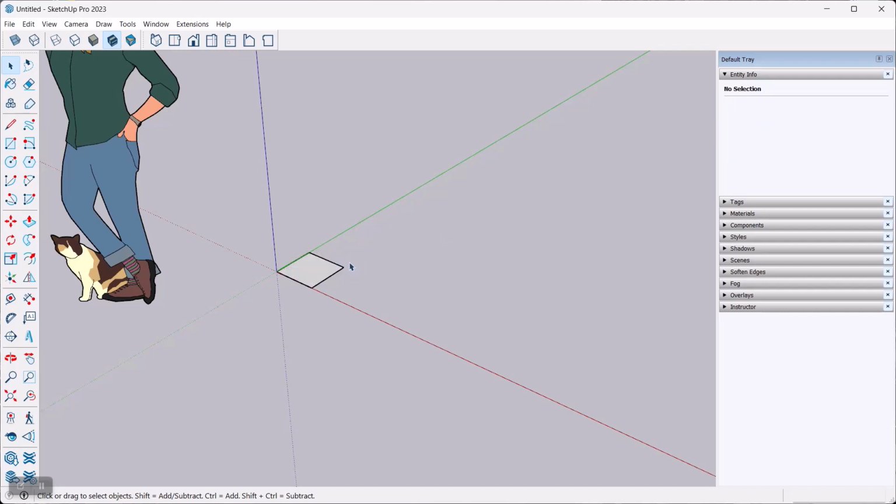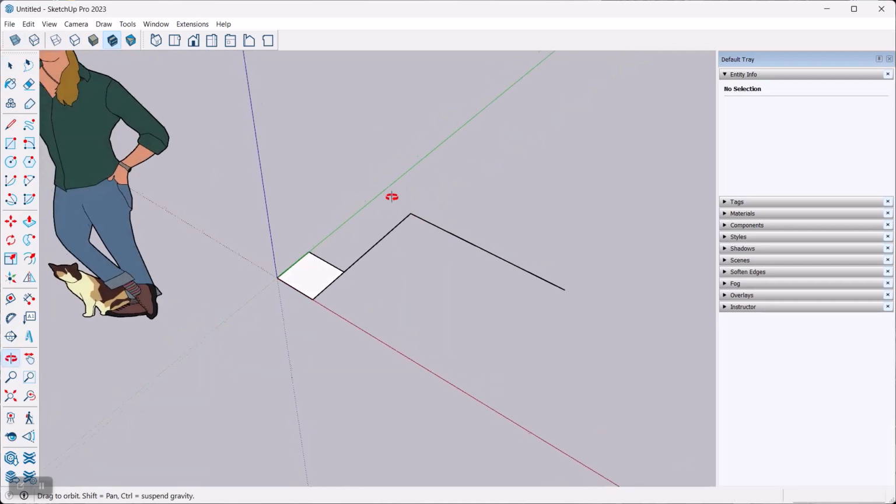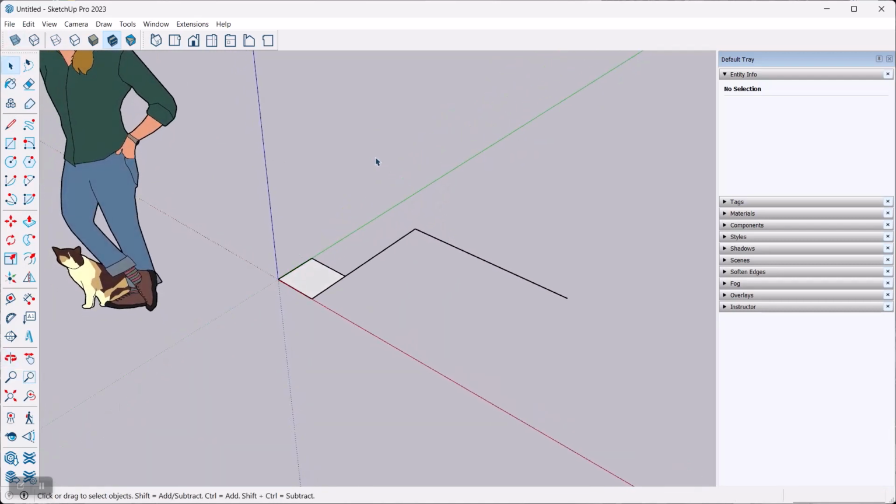Work with units as much as you can. Those work with anything, of course. If you do a line, you can type in 24 for 2 feet. If you go over here, you could actually mix and match units. This is another little tip if you want to, or if you have to. I can type in 1M and I get a line that's exactly 1 meter long, even though internally SketchUp always uses inches. Once you work with units right here, you can use anything that it understands. All right, so there's my plea for units and precision and how to enter those.